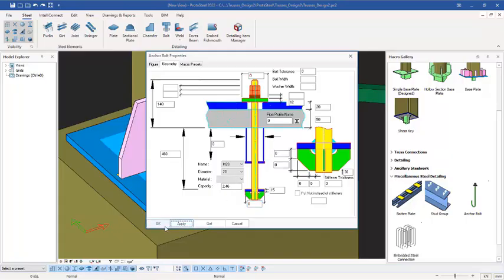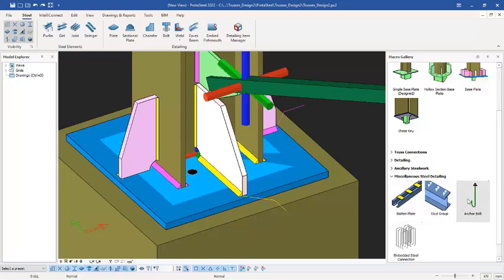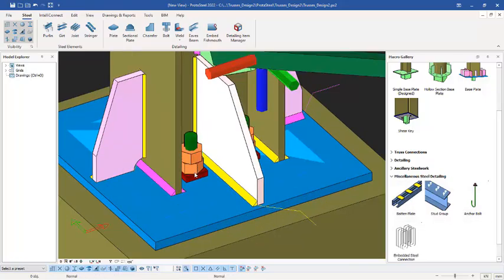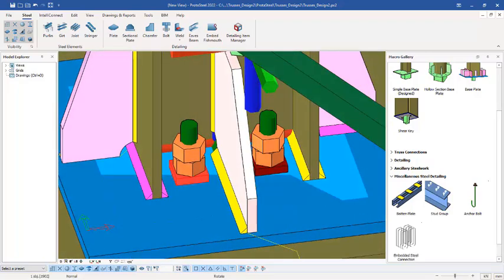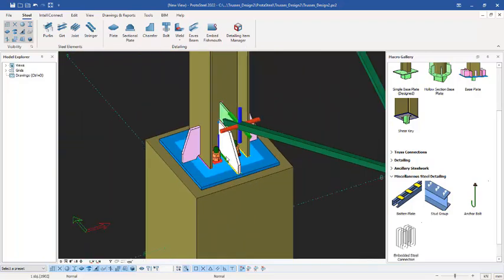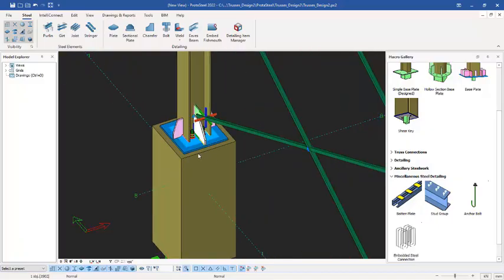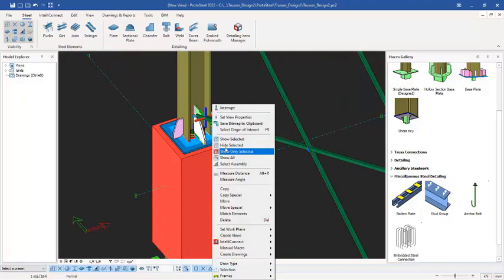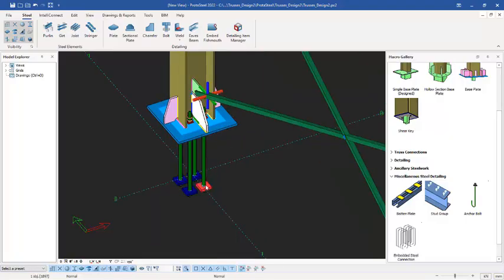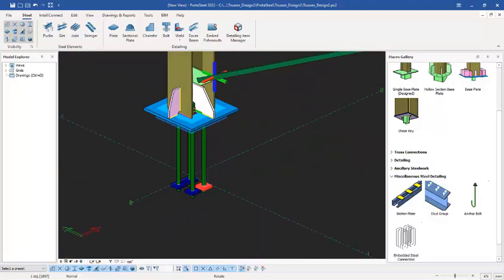and you can apply it and okay. So click on that, right click and select this. So you now see we have gotten rid of that bigger washer. We have only small washer and 2 nuts right there. So this is good. This is how you set your base plate. You can actually hide this to see what you have done. So this is what we have. This is the base plate, well designed like this.